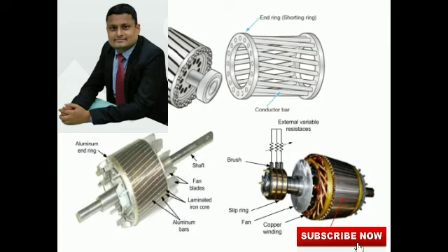Actual width of the rotor teeth is the rotor slot pitch at root minus slot width. This should be more than WTR minimum. So WTR equals pi into (DR minus 2 DSR) divided by SR, minus WSR. This should be more than WTR minimum. If this is not matching, recheck the standard table and get it matched.